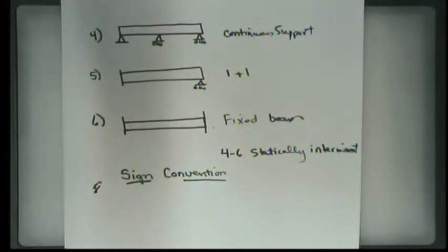For shear, or a vertical load, the sign convention is simply a convention, because a load in one direction is counteracted by a load in the other direction. Every single time. Has to be, or else something's going to move. However, we have to adhere to a convention in order to understand later if V's or taus add to each other or subtract from each other.